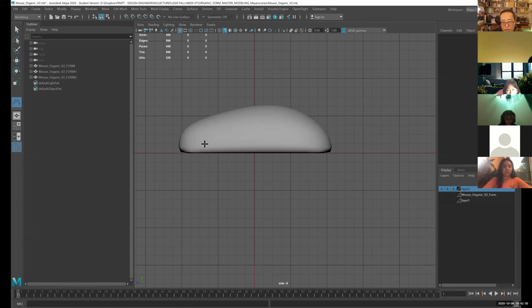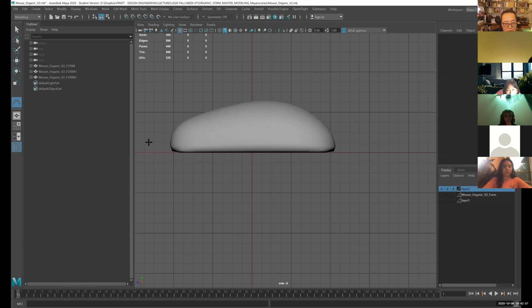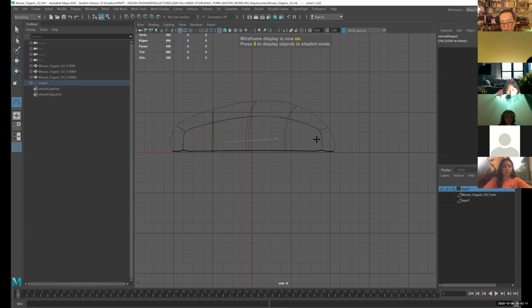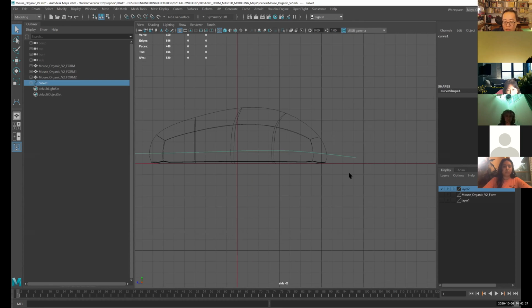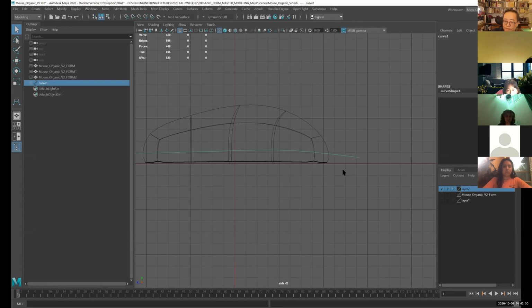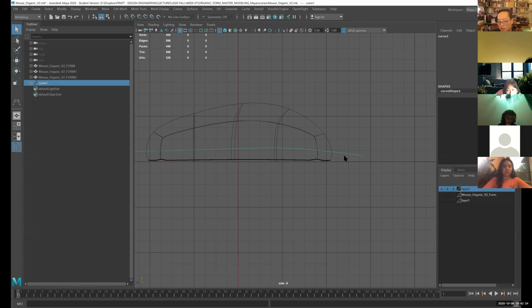And this is the front and this is the back. If I just draw some curves here, I'm taking the shading out just so that you can see the curve, okay? It can be straight, or it doesn't have to be straight. If it's straight, it's going to represent a flat, one-sided flat mold, which is less expensive. But if you really need a three-dimensional parting line for molding, then you can have a curved version. It all depends on the outermost profile silhouette of this form.